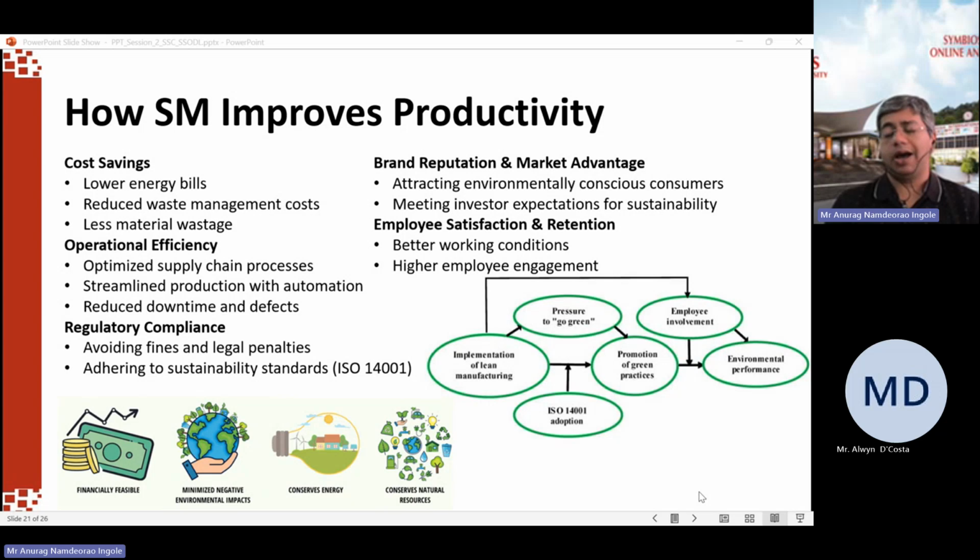An aspect of TQM is total productive maintenance. Some of the tools that we use is OEE, which is overall equipment effectiveness. If you are following that approach and using those tools, the equipment that you are using for processing your raw material will have reduced downtime. And you will have higher operational efficiency because of lean, because of your process changes. Because of the training and development of your human skills, you will have fewer defects. Fewer defects means higher efficiency.